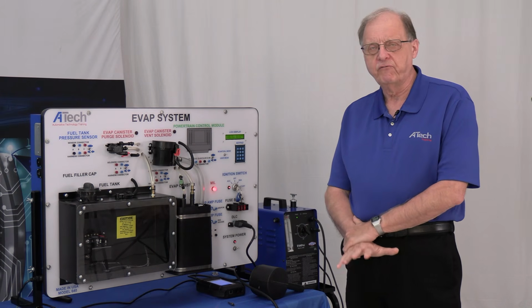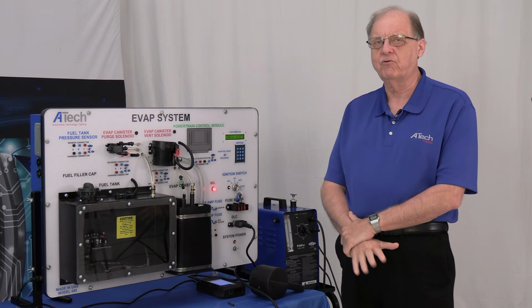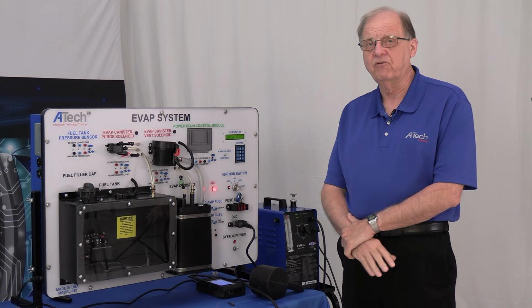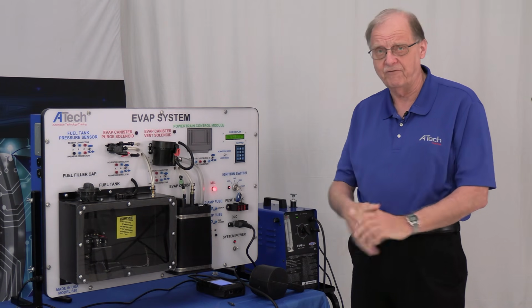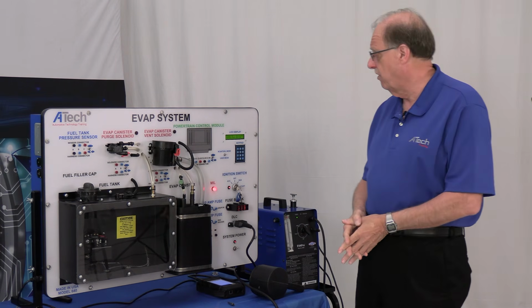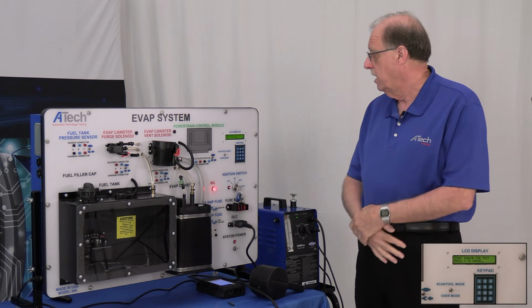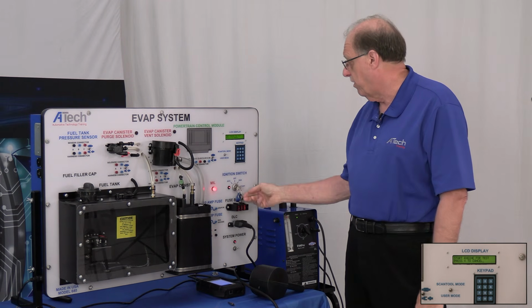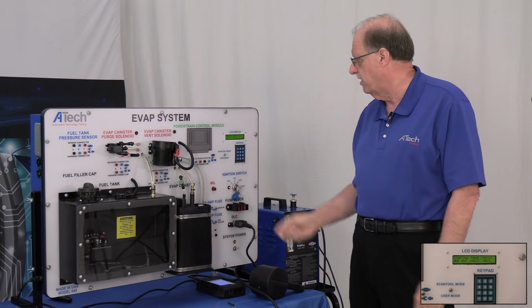Okay, we're going to do a service bay test on this particular vehicle. Now you're probably going to need the factory scan tool to do this test. Some of the aftermarket scan tools do not include this in their menus; they have other tests you can do. So the first thing we've got is a service bay test, and we're going to hit number 1 on that one. The first thing it says is start the engine for the test and press star to cancel, but we're just going to start the engine up.